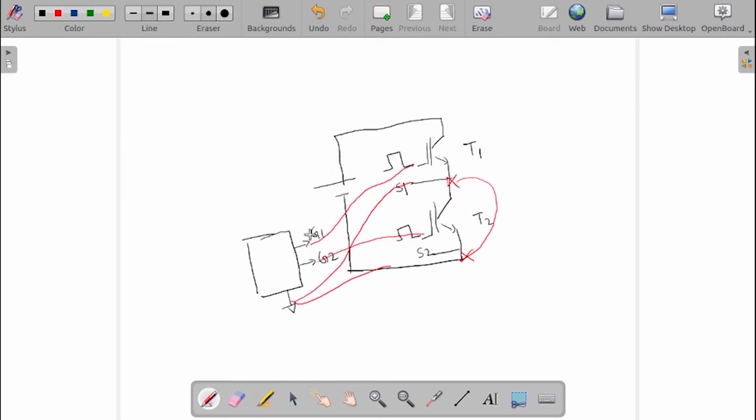So what you have to do is you will have to have a gate pulse for the top switch and the bottom switch in a totally isolated manner. There are different techniques for this. You can use opto-isolator based design, you can use pulse transformer based design, or you can use what is called a bootstrap based gate drive, like the one used in the IC IR2110.